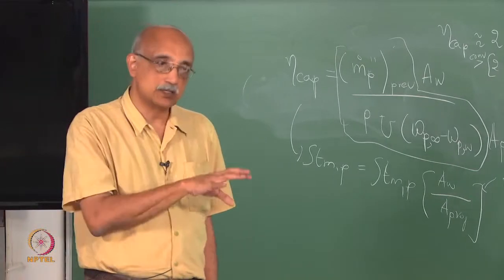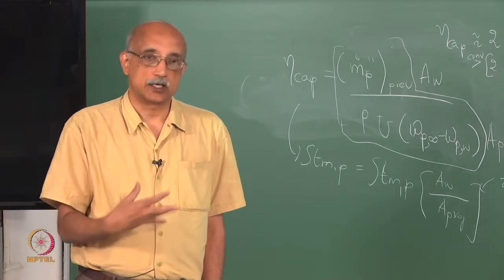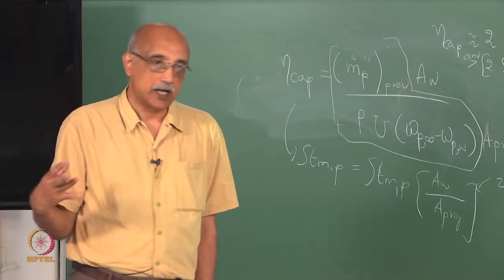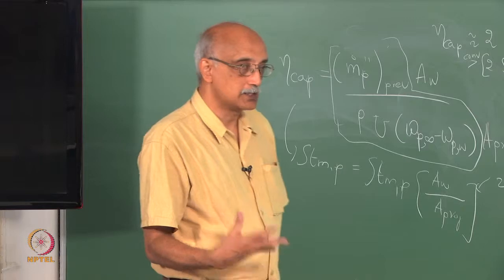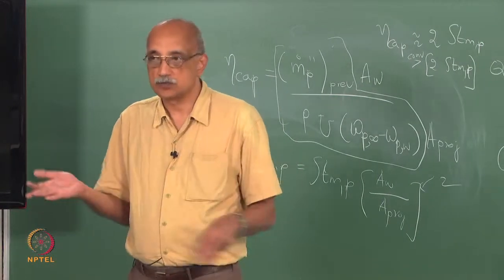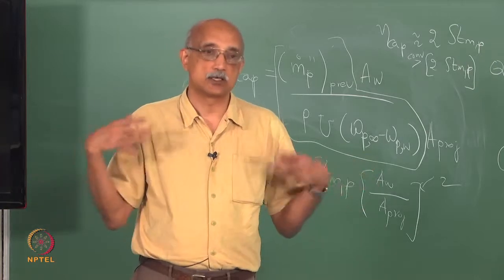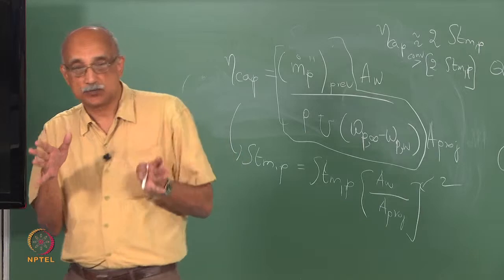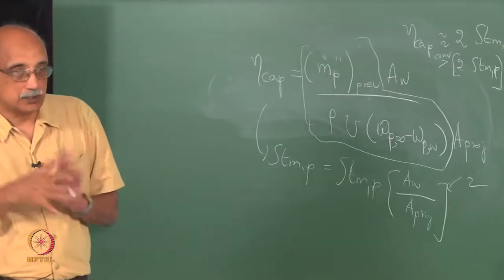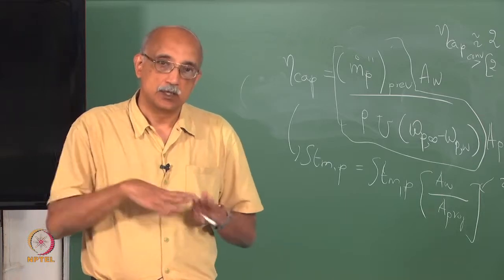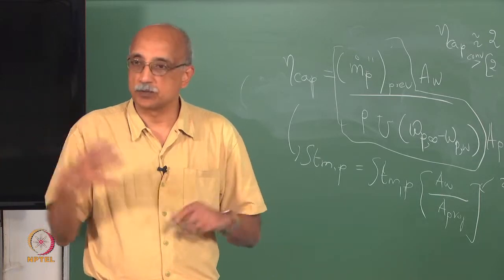At extremely small sizes, diffusional mechanisms can cause deviation of particles from the streamlines of flow and thereby enhance capture rates. And similarly, at very large sizes, inertial mechanisms can cause departure from streamlines and enable capture. So the minimum in capture efficiency is reached for an intermediate size where diffusional effects are weak, but at the same time inertial effects have also not picked up in magnitude.